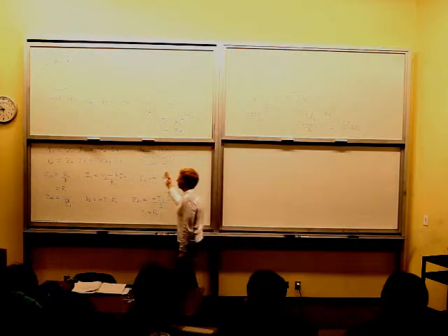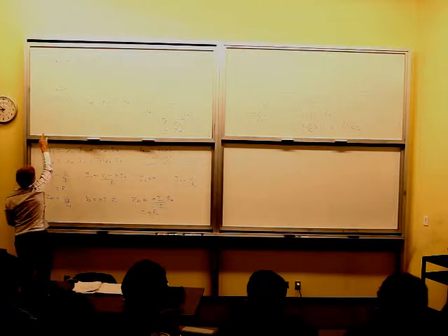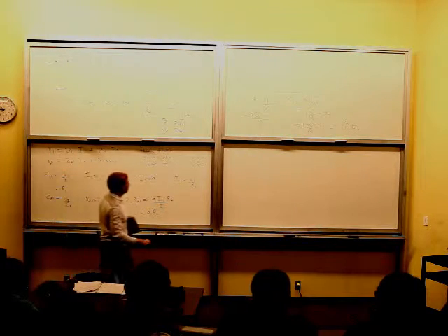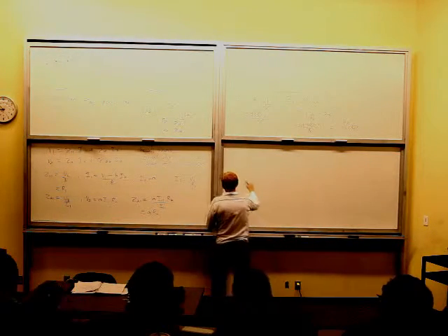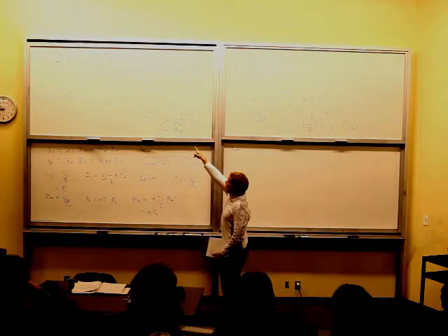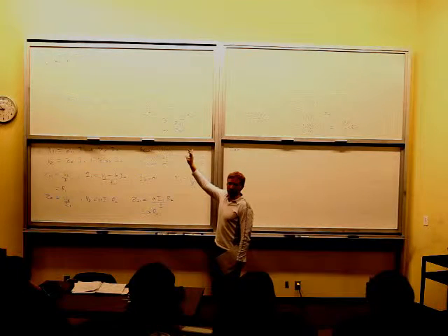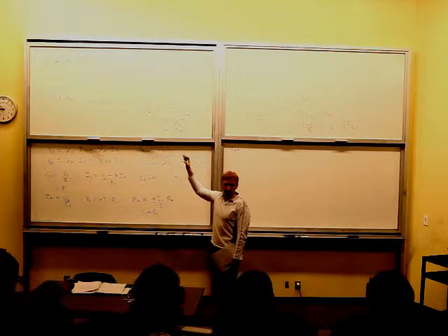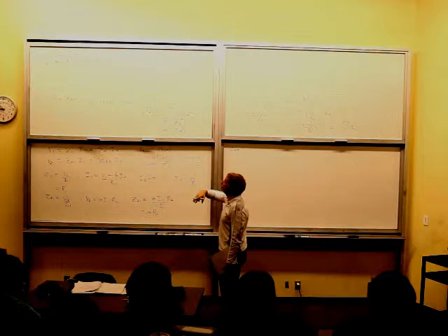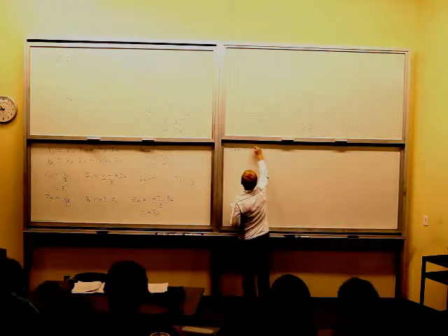Now what we're going to do is start looking at the other side, and open circuit that side there. So we know that I1 must equal 0. So we get here Z22. Since I1 equals 0, A times I1 must also be 0, so there's no current coming through that current source. A current source of 0 looks like an open circuit, so that's just gone. All we have is R2. I can just immediately say that Z22 is R2.